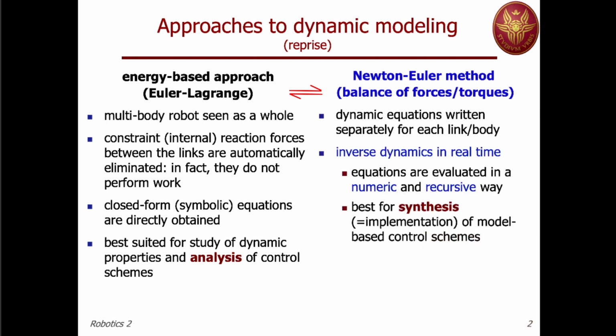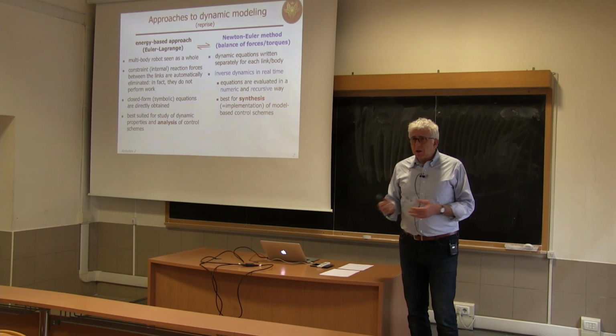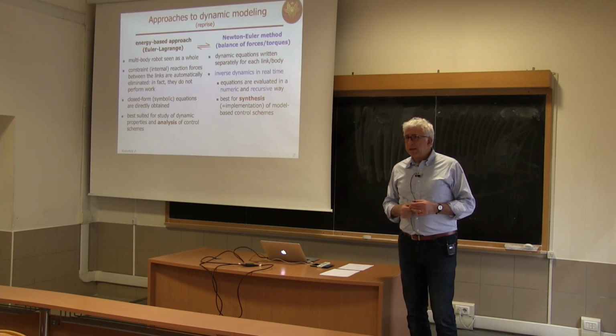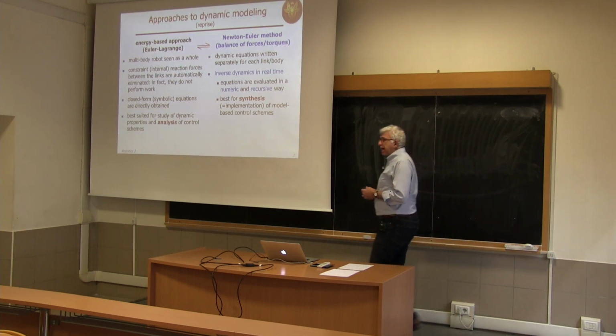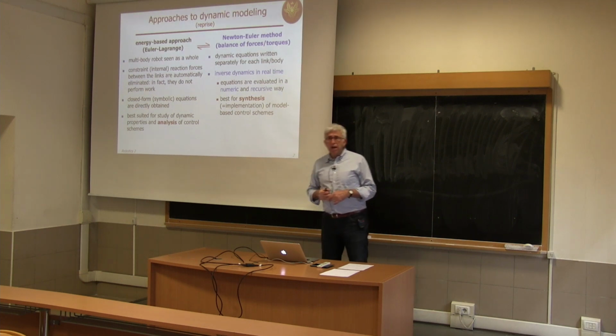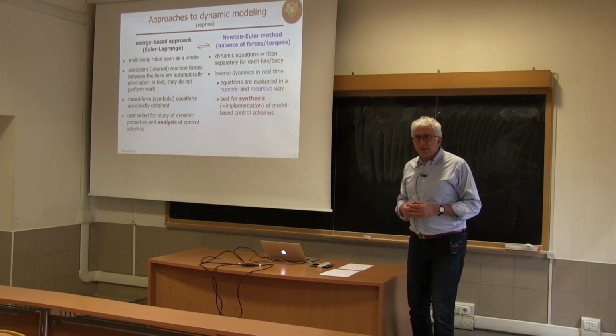And then we can combine all of them together and, in fact, substitute quantities from one equation to the other, using also the fact that in this equation acceleration comes out together with angular velocity. We will see this in detail. And all these quantities can be computed, again, in a recursive way, using the moving frame idea, much the same way in which we computed omega_i and v_i and then v_ci, so the velocity of the center of masses, with the moving frame formalism in the efficient implementation of the computation of kinetic energy.